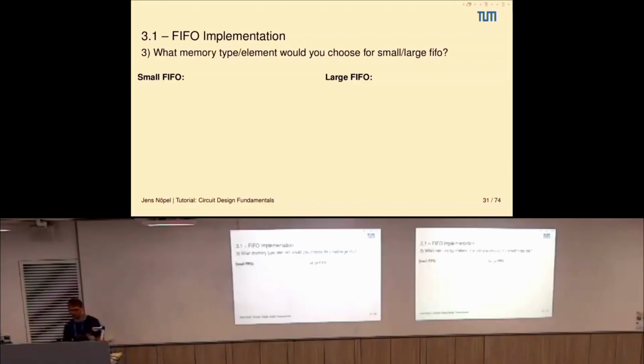Usually you don't use DRAM for FIFO implementations on chip. You could realize a FIFO using DRAM, that's not an issue, but it's not what's done if you use it as a module in between different clock domains.